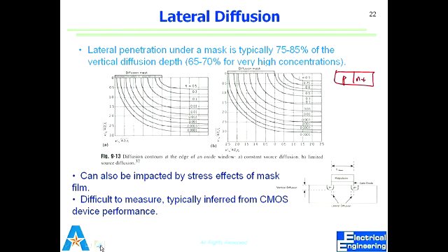Now I don't have to cut it, slant it. I can just put the probe on the surface. I can remove that oxide and now measure. I know where my oxide was supposed to be. And now I can measure and see how the profile changes. Right? At high concentration, it will be less resistive. And of course, that will give me a surface profile of the dopant concentration and vertical profile. That's exactly how it is done. I'm forgetting what that process is called. I'll find out. Right? Question?